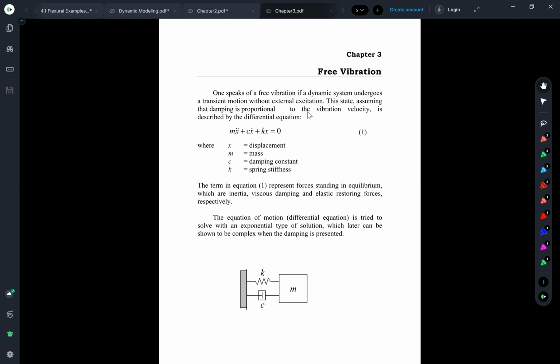And we try to get the behavior, the solution, or the maximum vibration of those quantities. To do so, we represent those real buildings and bridges by one physical system which contains only one degree of freedom. For the building and for the bridge, we represent with the same thing: one mass, one stiffness, and one damping.